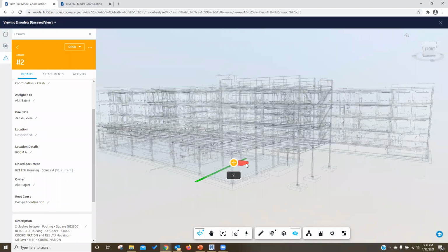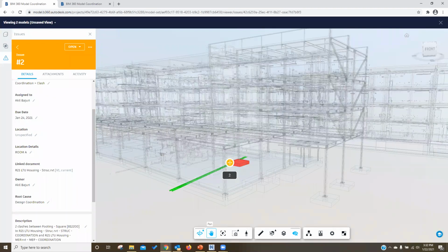Okay. And while waiting for the questions, I would like to show a bit of features on how you can use Navisworks to open up the BIM 360 model. So for instance, you are the coordinator or BIM manager. You may want to open up the models using Revit or Navisworks, but you don't want to download at all. But you have to make sure the same credentials are used for the sign-in information, and then you will get to access the models straight away from Navisworks.